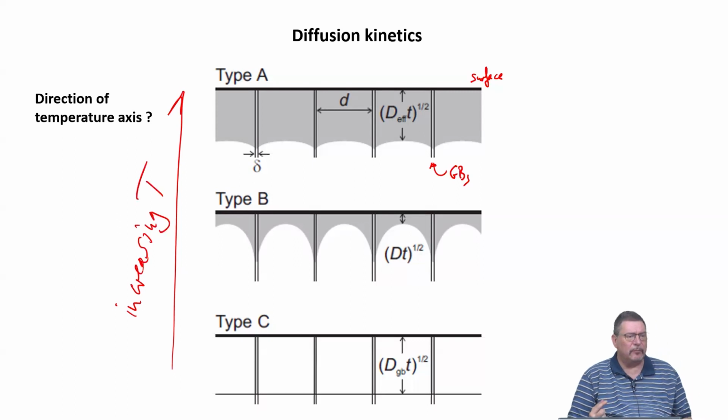So it means that if we go to very high temperatures, the diffusivity in the volume will become larger. Also, diffusivity in the grain boundaries become larger, but the material that has diffused along the grain boundaries also out-diffuses into the volume. And this is why what you measure later on will be affected mostly by volume diffusion.